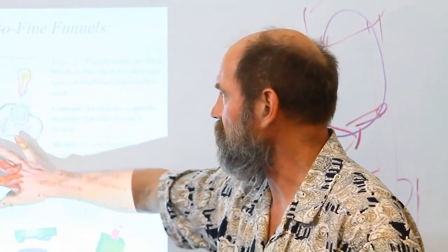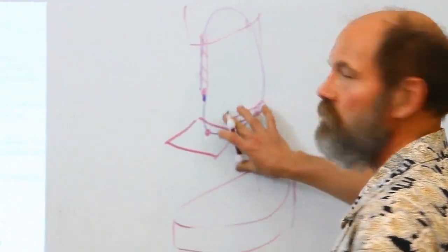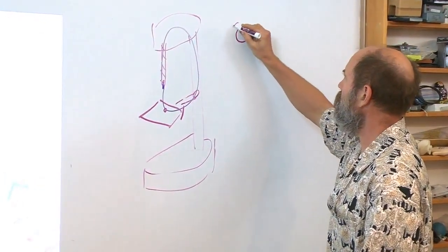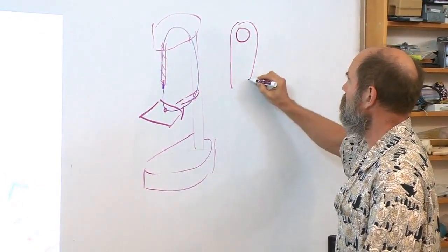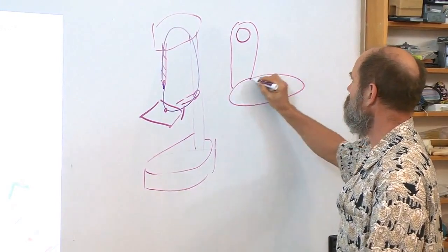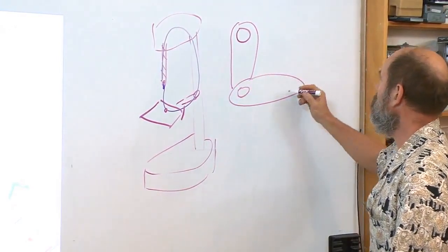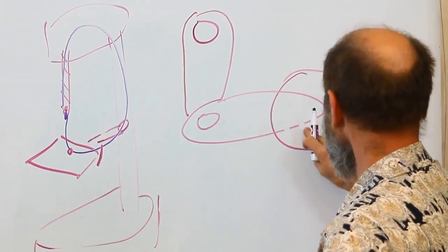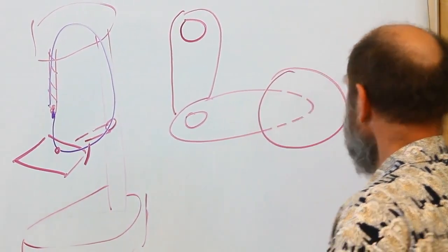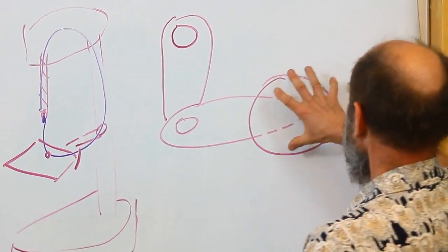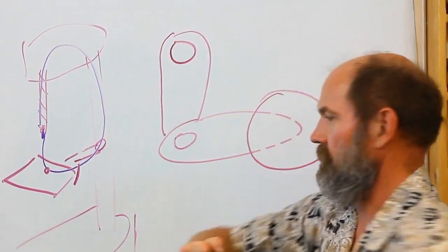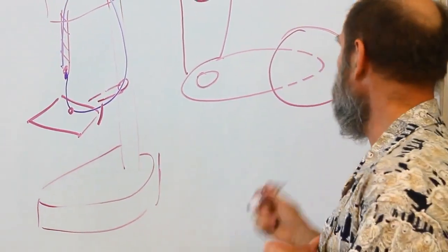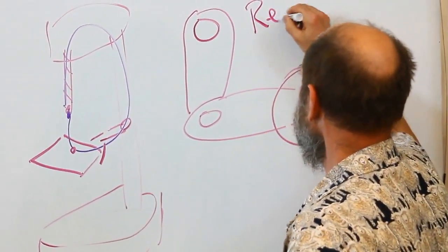Once you have the concept you like, and let's say we'll pick, here's 2 concepts, for example. One concept for the table is, if I'm looking down on the drill press, I'm going to have an arm and then another arm that comes out, and this is looking down on it, remember, here is the table. So this becomes a dashed line. And then now I position the table by moving these 2 arms, like this. This is a concept here of, these are called revolute joints.